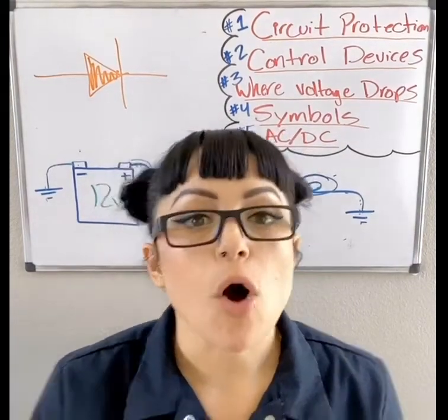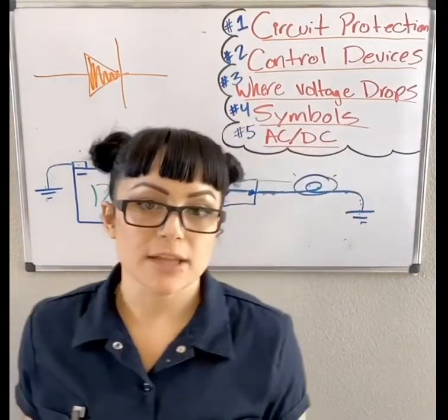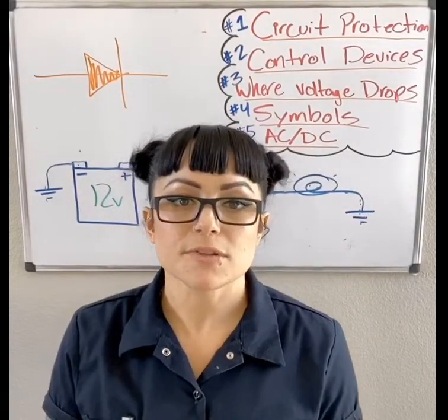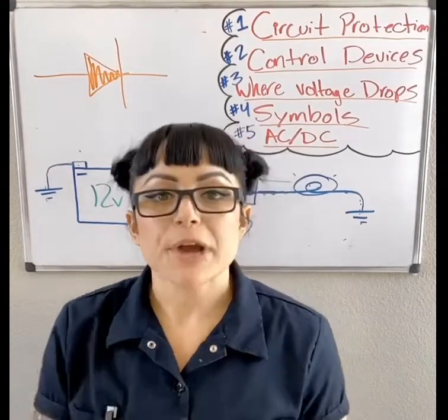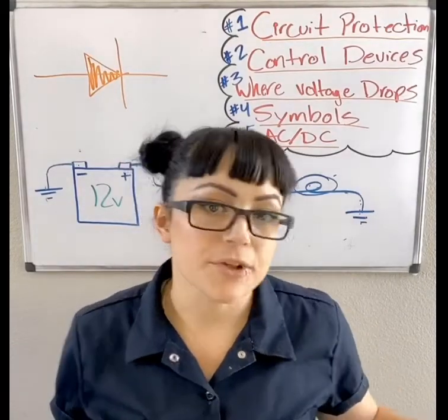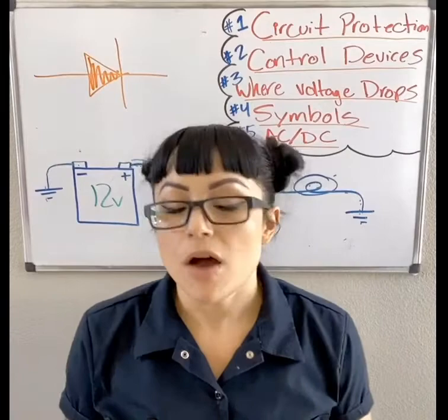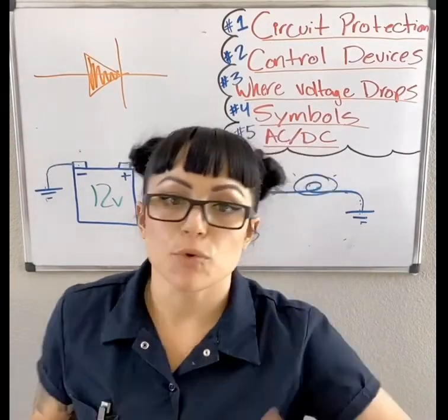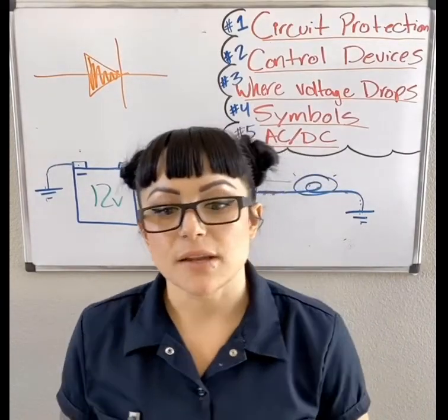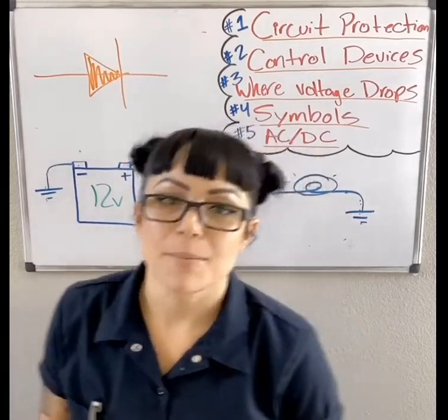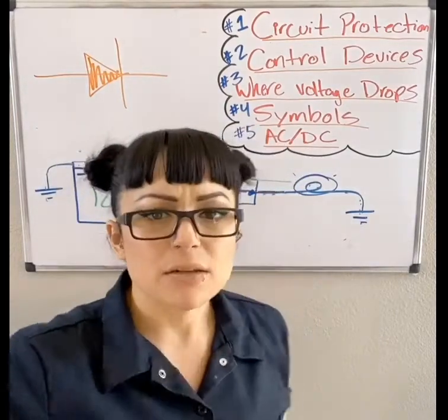They are used all over electronic circuits inside our vehicles. In one direction, it will act simply as a wire, a regular conductor, and have no drop of voltage at all. But in the opposite direction, it will not allow current to pass, and so you will see a voltage drop. Again, more for an electrical class.